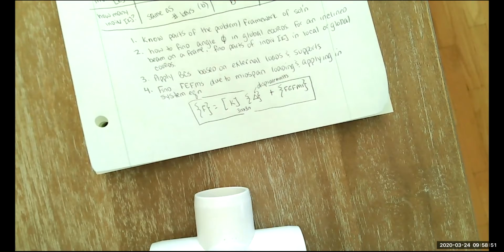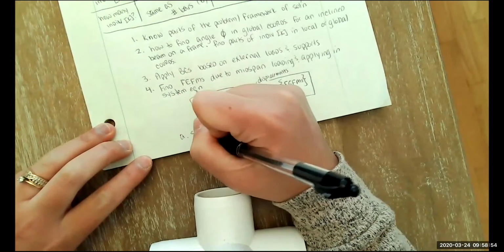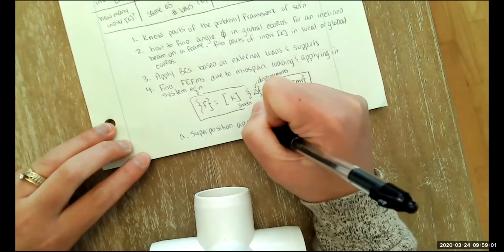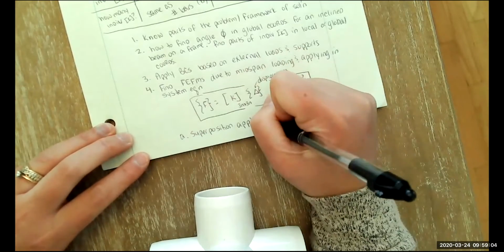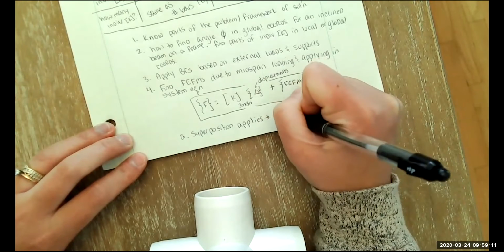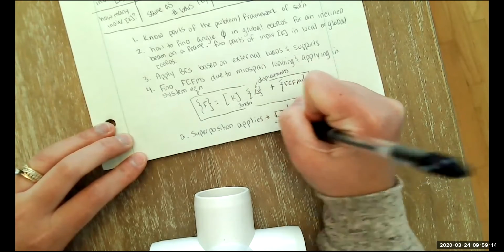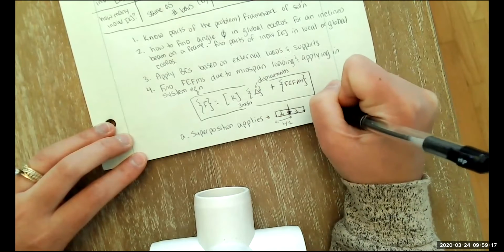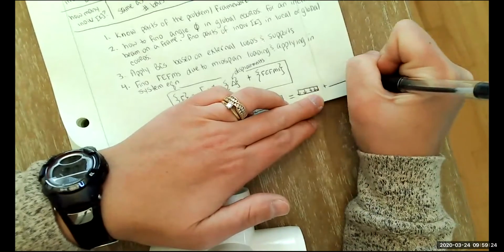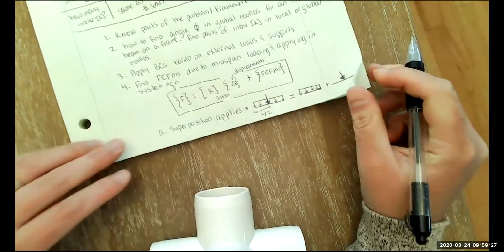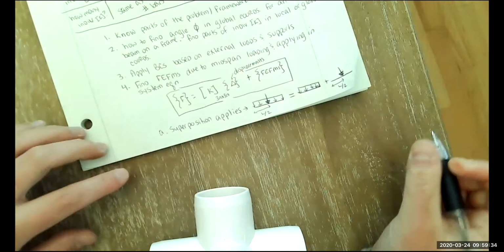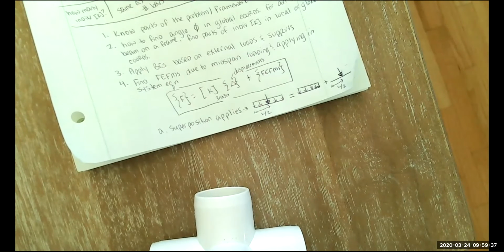to find that vector of fixed end forces and moments depending on any load condition. Remember that you can use superposition to find fixed end forces and moments for complicated situations. So for example, if I have something that looks like this with a distributed load and a point load, and this is L over 2, this is equal to the fixed end forces from my uniformly distributed load across the entire beam, plus the fixed end forces and moments due to this point load applied at L over 2 across my beam. So we had some examples on that in homework 5.